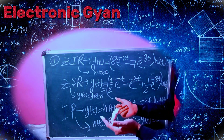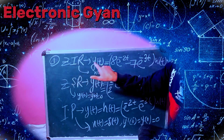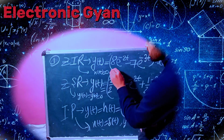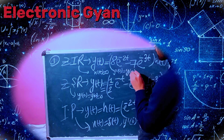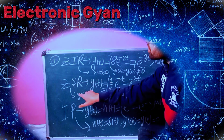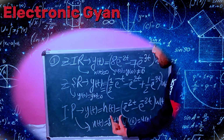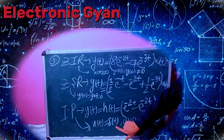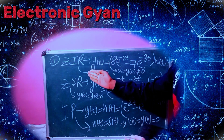This is the zero input response, zero state response, and impulse response of the system in control systems and signals and systems. How to calculate that? The main basic concept is that zero input response means input is 0, then the response of the system is due to initial condition, which is not equal to 0. Zero state response means the response is due to input where the initial condition is 0. And impulse response means my response of the system is due to input that is an impulse, where the initial condition is 0.